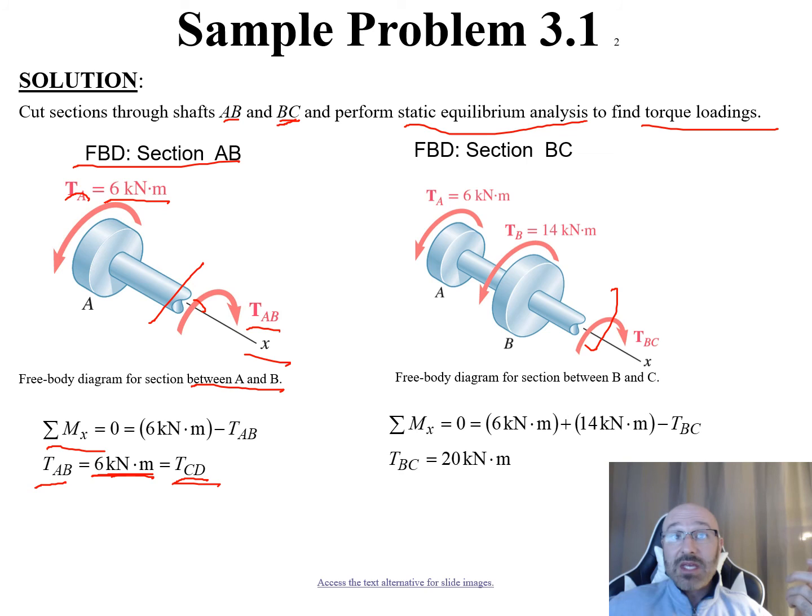Well, there's still AB before it. So this is great that we solved for AB first, and now we can go on to our BC right here. We can go through this and again draw a free body diagram. I have my counterclockwise rotation of 6 kilonewtons here. I have my T sub B here, giving me the problem statement as 14 kilonewtons going counterclockwise.